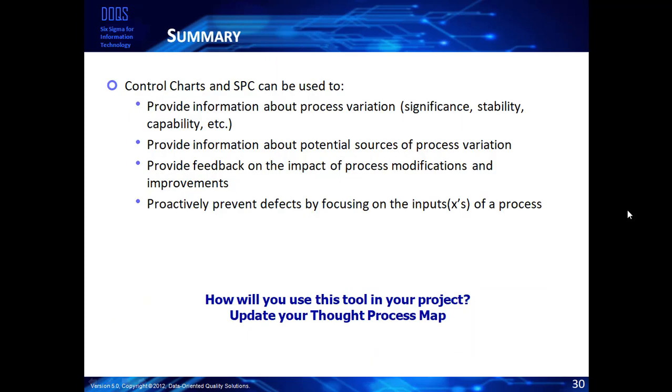So finally, SPC, or statistical process control, is our tool for measuring the voice of the process, for figuring out if it's stable and reliable. Can we accurately use statistics to predict future behavior of a process? And we can if we can show through our control charts that the process, the way it's behaving, is in fact under statistical control. That doesn't mean it has no variation. It might have an enormous amount of variation, but the amount of variation remains fairly constant and the process stays within its limits.